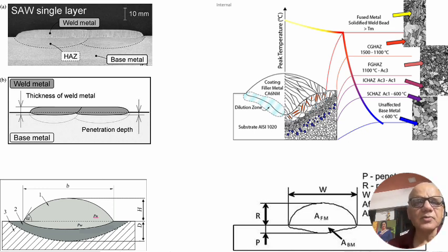And this is a beautiful picture which shows how the dendrites and the solidification are going to happen with the number of passes, and each pass. So you observe here that we have the penetration side, the heat affected zone, but important is that you see here even the angle is also mentioned. So we should have a very narrow depth of penetration as seen here, and as wide as possible. It should not be sharp. In our next slide I will show you how a typical butt joint weld penetration looks in cross section.